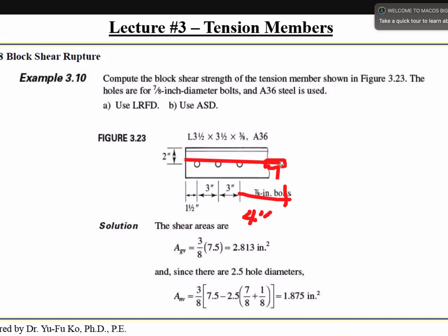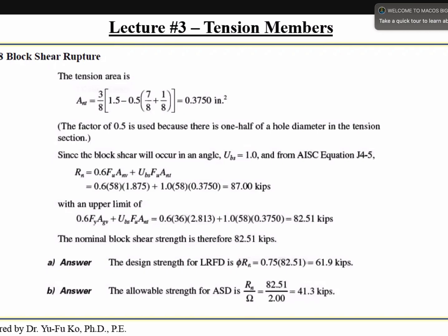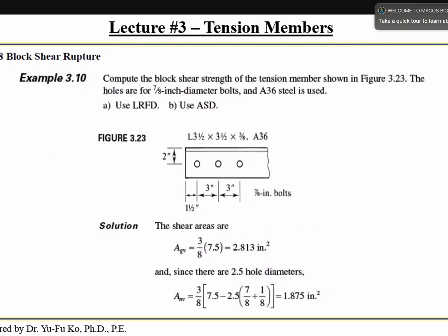If you have both cases like this, you're just extending your shear area and tension area like this. Still plug shear, okay? Well, Professor, if that's the case, then only the shear area will be affected, right? And the tension area will be the same. Yes, you're correct. You are extending the shear area. That's correct.